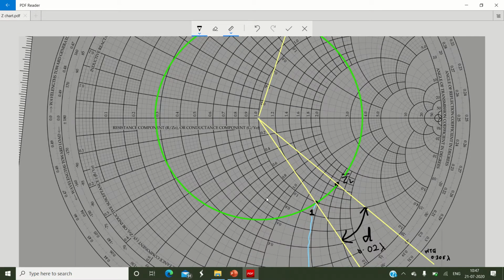As per earlier discussion, we know that this particular point on the extreme left hand side of your Smith chart, on the innermost periphery, represents Z equal to 0, because here the impedance is minimum. When you go along the real axis to the right and reach the extreme right hand side, Z becomes infinity, as an open circuit.